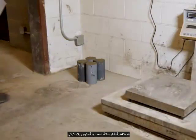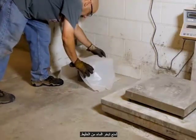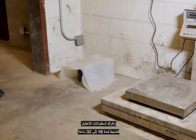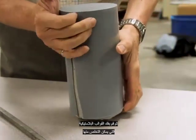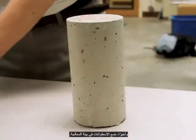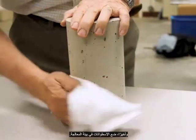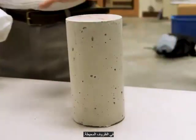Cover the molded concrete with a plastic bag to prevent evaporation of water from the mixture. Leave the test cylinders to set for 16 to 32 hours, and then strip the disposable plastic molds from the concrete specimens. Finally, place the cylinders in the curing environment. In this case, the cylinders are left to cure in ambient conditions.